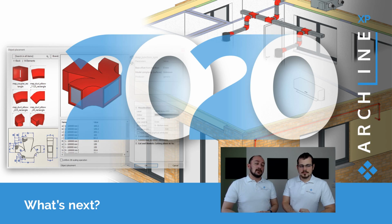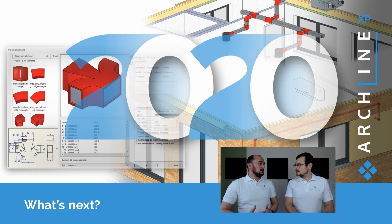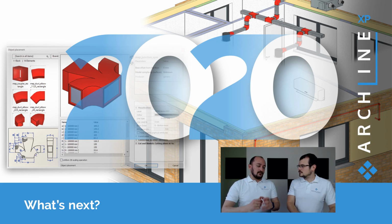You can also build up systems like this. In certain countries, it is a must to represent at least the basic HVAC system or a cooling system or whatever with the electric symbols you have to represent on your drawings. We will also talk about how to draw and document electrical switches and the connections between all the light sources wherever you have them in the building. And the software will also be able to tell you if there is a simple issue with that system, for example, you have forgotten connecting a switch with a light bulb, and the software will give you a warning, and it will also highlight what the problem was, and it will help you to fix that. Very clever. So that's what we are going to have in about 2 weeks.